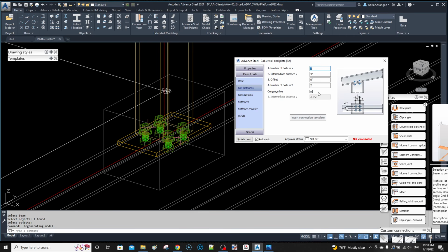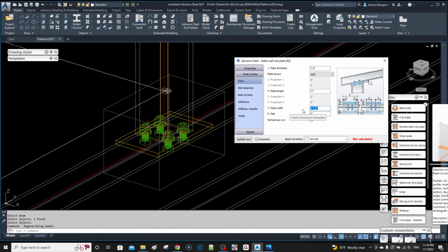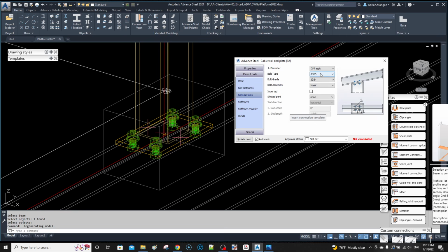And that is why that was set to 6.5, because it will give me 1.5 inches either side. But 1.25 is fine, 1.25 inches either side. So that's 2.5, and 3.5 is 6, which is what I have it set to. So 6, or you could change it back to the 6.5, just to be safe in case the holes are off a little. So maybe safest thing is 6.5. 6 is fine because it's still within the standard. And then 3 inches, so we want 3 inches plus the 5 inches for the post, which is 8 inches. And then we want to also change those bolts to TC bolts, and that looks good to me.